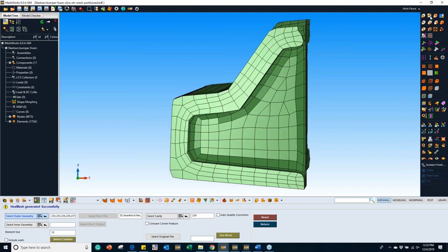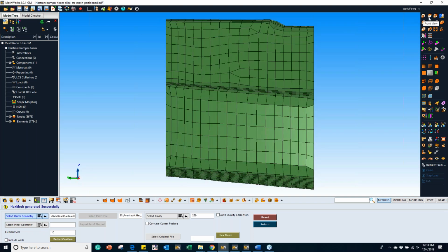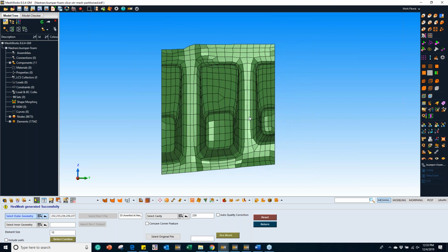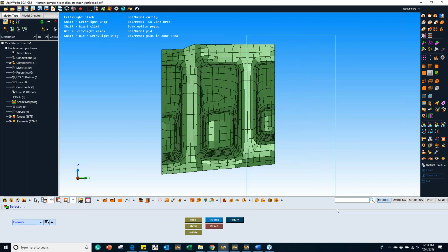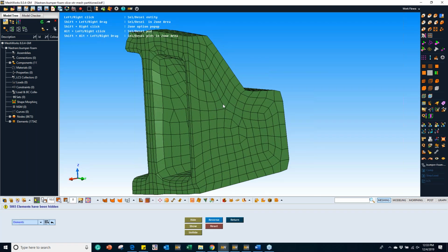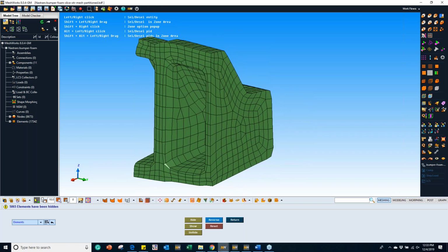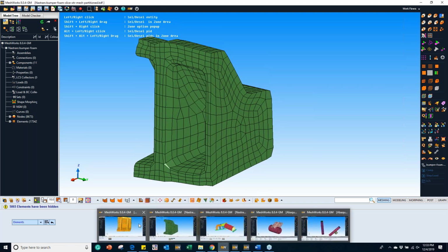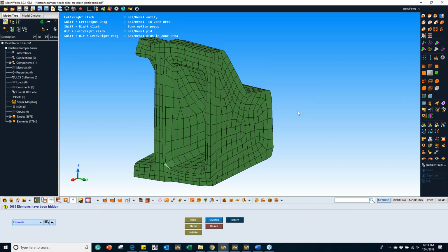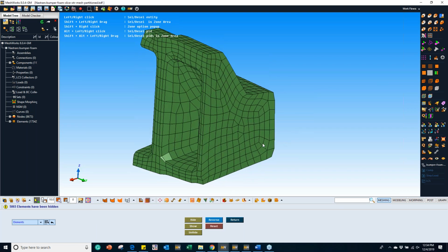So to summarize the steps again, you're creating a brick layer inside the geometry from step 1, and using that brick layer, now in this auto hex mesh, you are doing a plastering, outside plastering, to adhere to the true CAD geometry. Okay, and both steps are very fast steps.